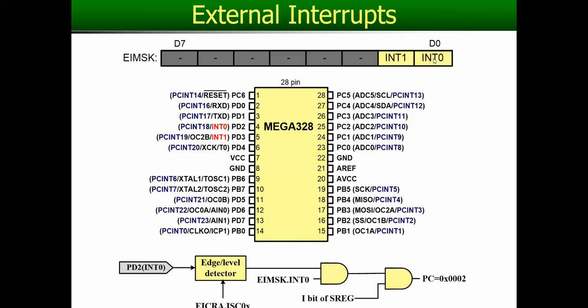Okay, that means you're masking the interrupt. So externally, something has happened in the door, but you're not listening to it anymore. You just say that, hey, you can ring the bell, but even if I listen to it, I will not respond because I'm busy, or I just don't want to entertain you at this time, unless the software programmer, the embedded system developer, tells me to. Again, how would he tell me? You just go and put 1 in this bit.